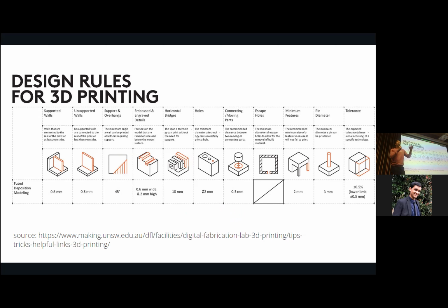Usually, you want the difference in size to be 0.2 millimeters on each side. So if it's a round peg into a round hole, there'll be a 0.2 millimeter difference in radius or 0.4 millimeter difference in diameter. You can even get away with a 0.3 millimeter difference in diameter, probably, which will make it about 0.15. So yeah, with those tolerances, it will get you a pretty good fit, but it's printer dependent. So if you have a question,